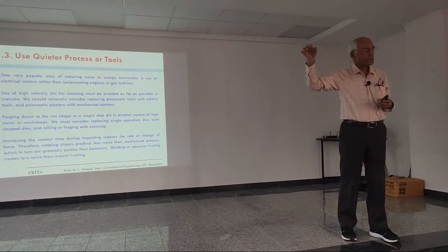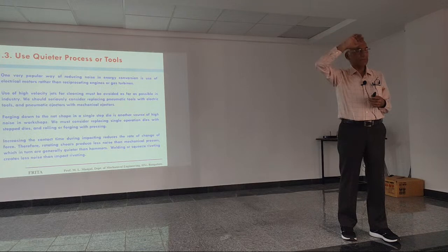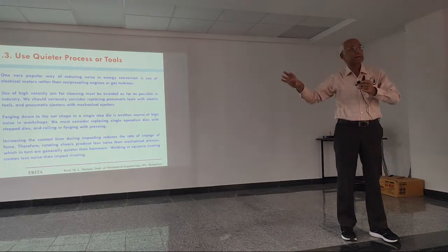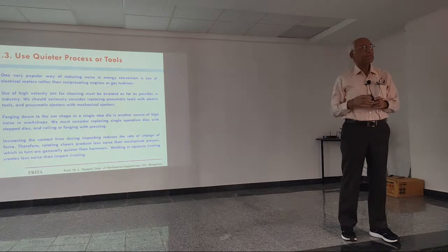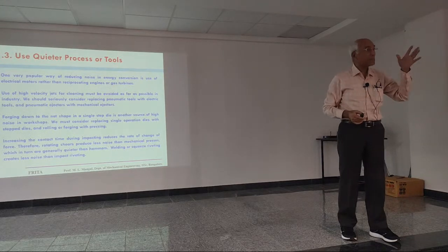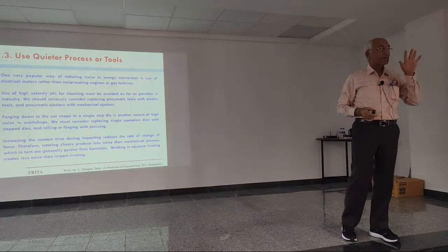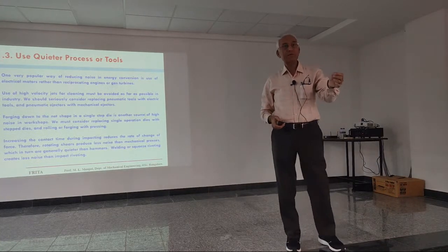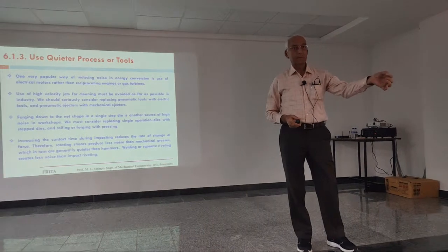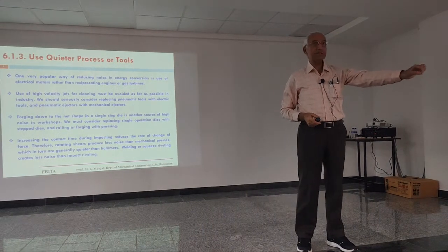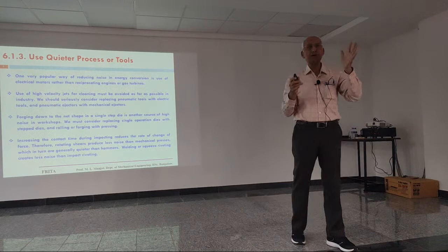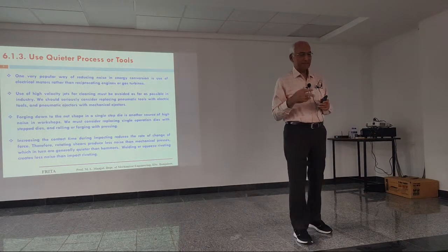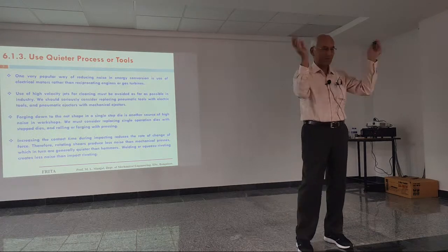I said, how did you fix the pressure of the compressor? No, it was already there. This joint was there. They are fine. Now I found that it was 7 bars pressure. 7 bars pressure he was using. So the air that was coming out was supersonic all the time. And getting shocks there, right? And using so much noise. And it was very, very bad design of the whole workshop.